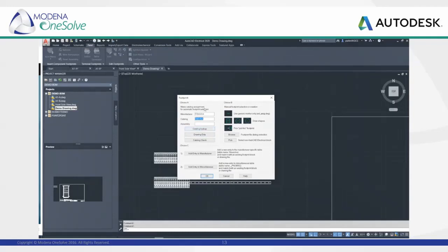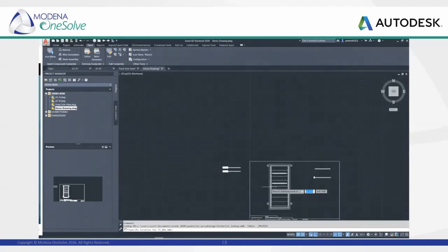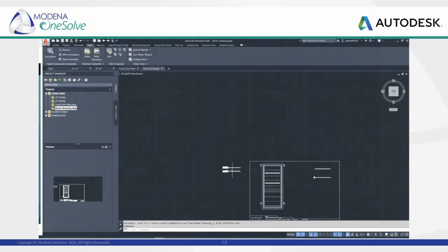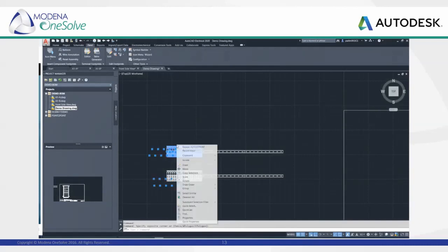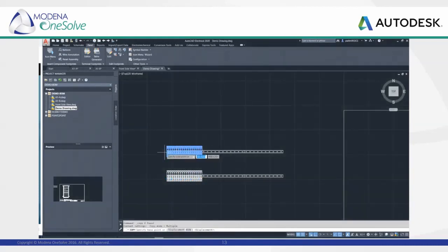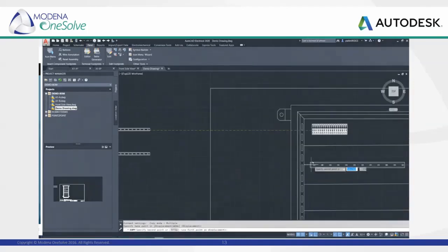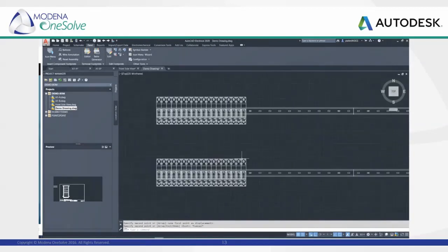And what I can do is quickly input some catalog data or head over to my catalog browser and do a search, but I'll just use this catalog item code SMS45A to quickly call upon my enclosure design. Head over to my workspace and place the entire enclosure. Now what I can do is simply copy the breaker information on the rails to the side, head over to my enclosure and paste.